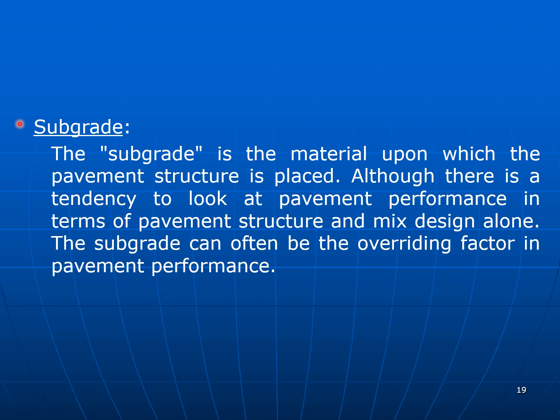Subgrade. The subgrade is the material upon which the pavement structure is placed. Although there is a tendency to look at pavement performance in terms of pavement structure and mix design alone, the subgrade can often be the overriding factor in pavement performance. So this point must be noted, that the subgrade can often be the overriding factor in pavement performance.